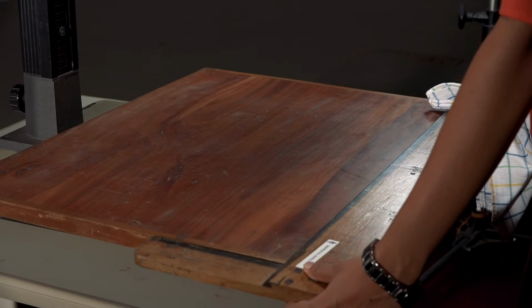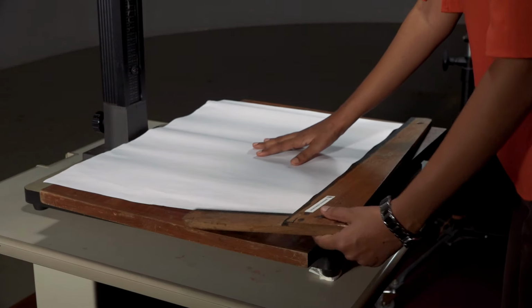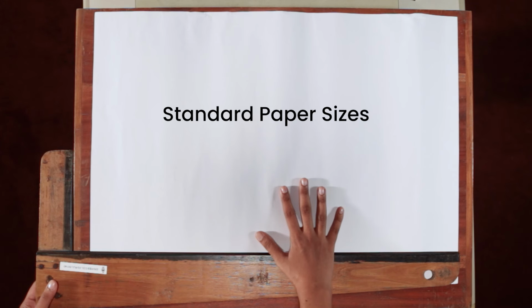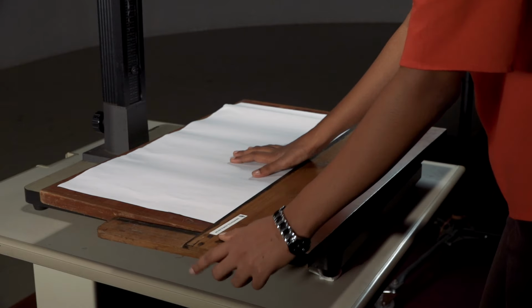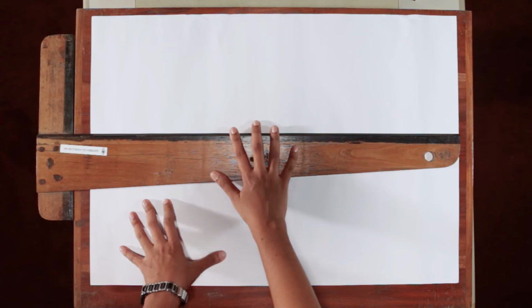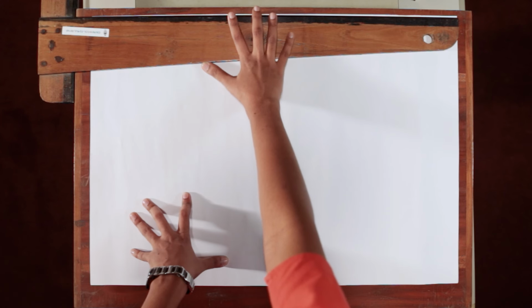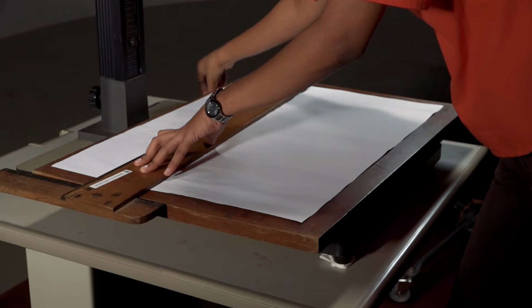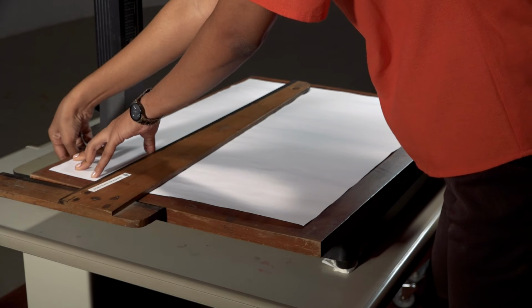For the current exercise, we will be using an A2 size paper which is 420 mm by 594 mm. After placing the paper on the drawing board, align the top edge of the board using the T-ruler as shown here. Then, secure the paper from the top edge only using the paper clips.